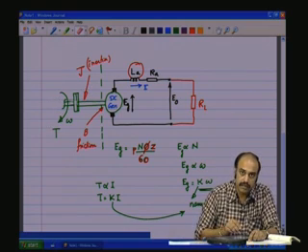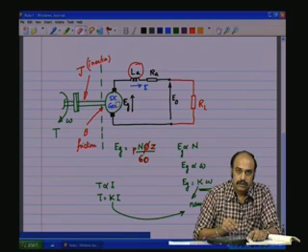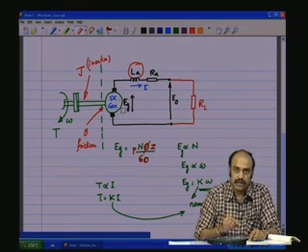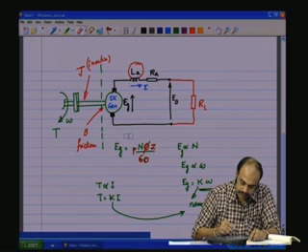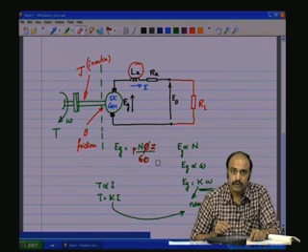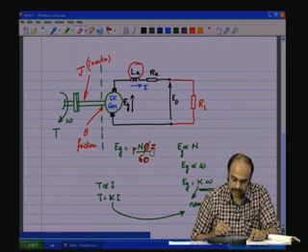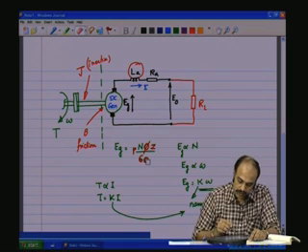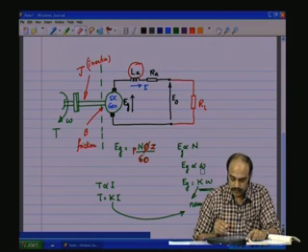So, the energy flows from the prime mover in the rotational mechanical domain, gets into the magnetic domain, and then from the magnetic domain to the electric domain within the DC generator equipment. The induced EMF EG is given by this equation which we have seen and discussed in the last class. EG is number of pole pairs P into N RPM into phi flux per pole into Z, the total number of conductors in the armature, by 60, a constant. As P, phi, Z and 60 are all constants for a given motor, EG is proportional to N, or EG is proportional to omega, that is radians per second.